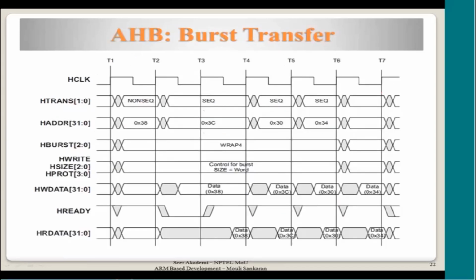And then bus transfer. You can have multiple transactions for a first non-sequential access. So different addresses are given now, as you see. And if you see, there is a bus transfer signal that is sent. That means it is communicated to the devices that the bus transfer is happening, and then the different data for those specific addresses are given on the bus. Okay, so they are all provided.